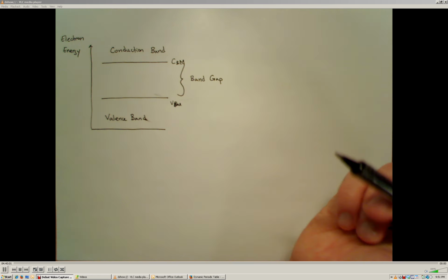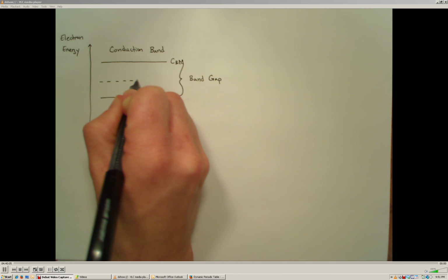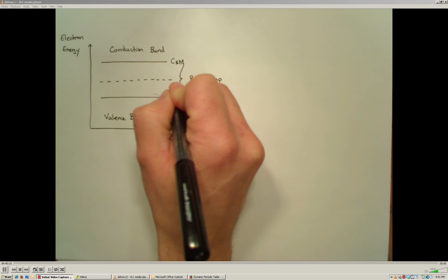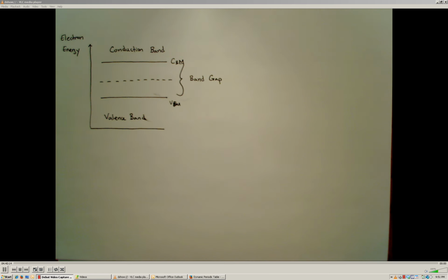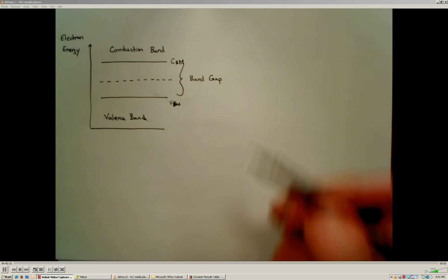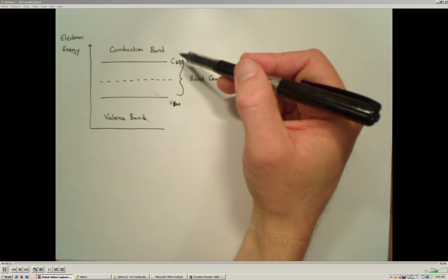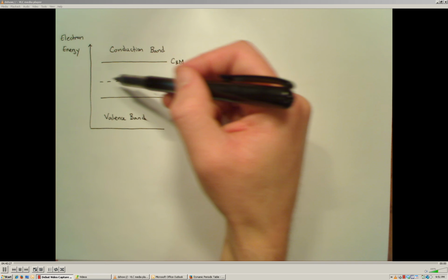But nonetheless, we established this thing that's called a Fermi level. And the Fermi level in a semiconductor like silicon lies right in the middle of the band gap. Okay, well, not all the time. We're going to talk about when deviations from that occur. But right now, if it's just a lattice comprised of all silicon atoms, it's going to have a band gap, and the Fermi energy level is going to reside right in the middle of that band gap.